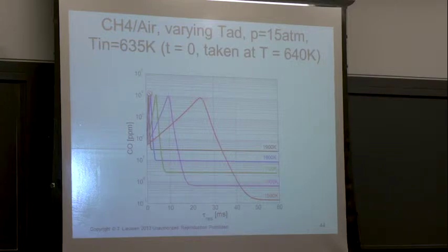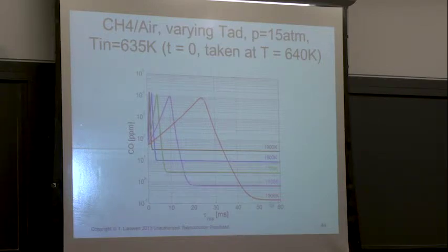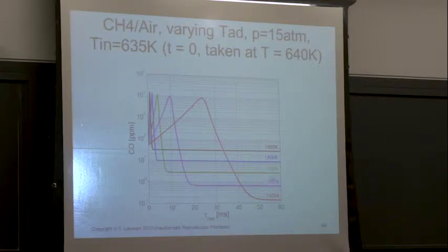If you quench a flame, or when you have incomplete combustion, it's a quick and dirty way to kill yourself. But it drops down. What's interesting is that as you go lower in temperature, equilibrium CO is lower. So you have higher equilibrium CO at 1900 K than at 1500 K. Does anybody know why that is?